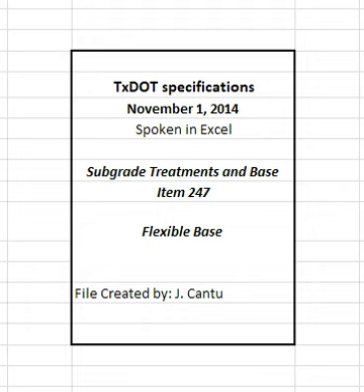4.4 Finishing. After completing compaction, clip, skin, or tight blade the surface with a maintainer or subgrade trimmer to a depth of approximately 1/4 inches. Remove loosened material and dispose of it at an approved location. Seal the clipped surface immediately by rolling with a pneumatic tire roller until a smooth surface is attained. Add small increments of water as needed during rolling.